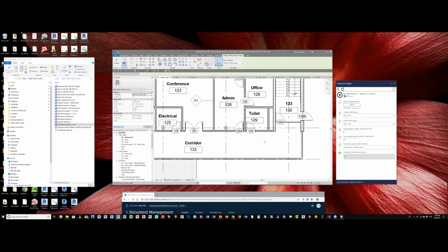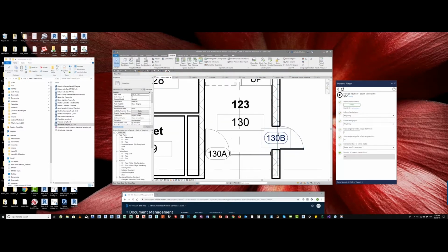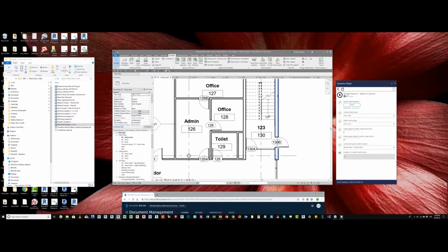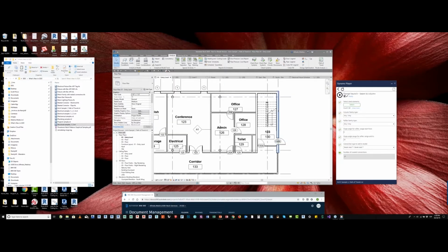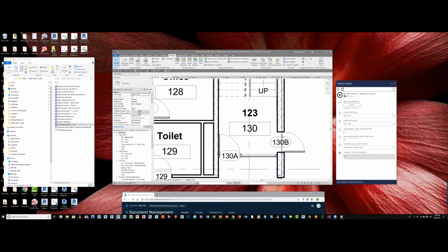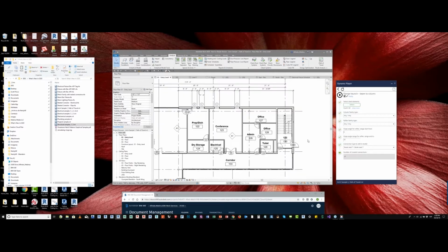Why does it not want to cross that door? And I found that the floor is the problem. So somehow we need to say the floor needs to be included in that list. Otherwise, the tool considers the boundary of the floor to be something that cannot be crossed, cannot be passed.